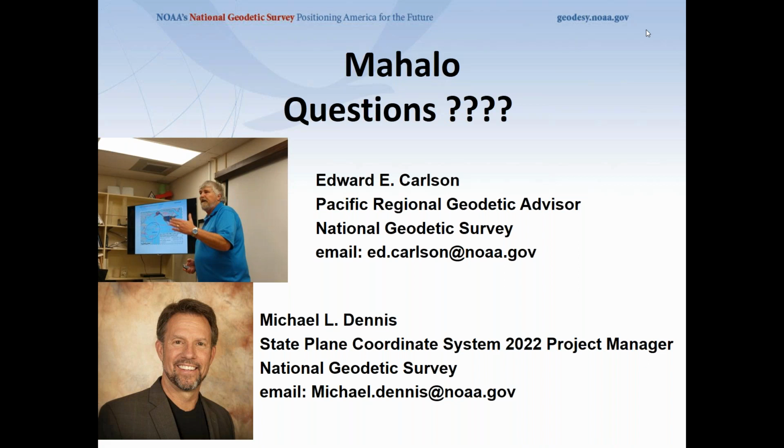Yeah, that's basically it. So a little background about this. Actually, there are a few states that have a single statewide zone, even though they're very large, in current state plane. For example, Montana. Montana had 3 zones for state plane 27, but has 1 for state plane 83. And when we started this project, we asked people what they wanted, and a very large proportion were super enthusiastic about having a single statewide zone, mainly for statewide GIS applications, say like a Department of Transportation or any state agency.